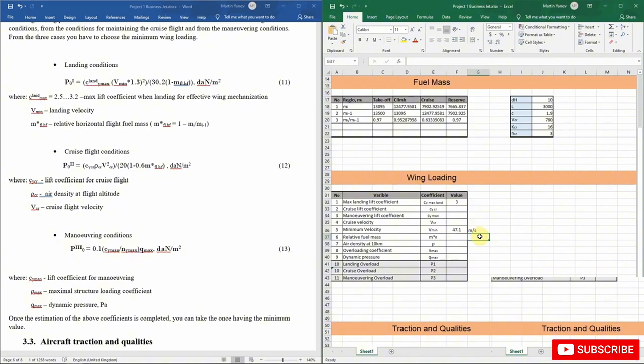Now, since we have the minimum velocity, it's time to determine the relative horizontal flight fuel mass. This is usually equal to 1 minus the cruise flight segment, because this is the horizontal flight when we're at cruise level. So I will simply write 1 minus this segment, as you can see here, and this will be equal to 0.366.